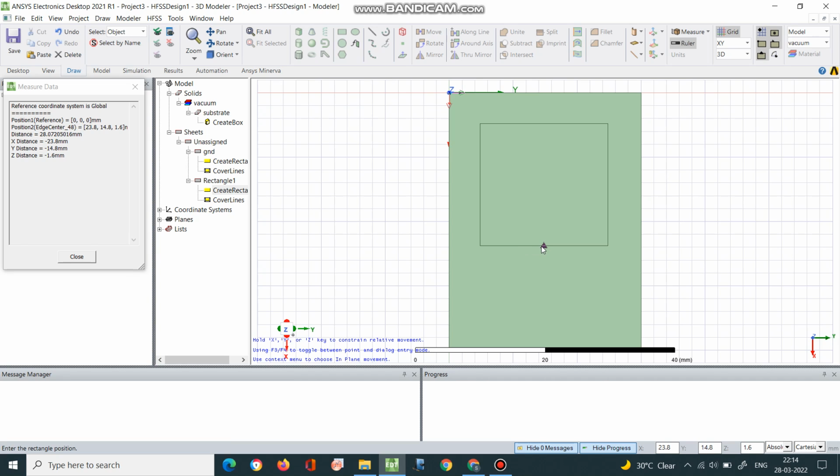For this also I'll be taking the same rectangle. Now when I am changing the position, the shape of the cursor is changing. Here it is like a rhombus, and in the center it is like a triangle. Just for my observation, that is to draw it easily, I'll be starting from the center because at the center I have to feed, but I'll maintain some thickness, right? So let us take the width of the line as 3 mm. But now I have started from center, so later I'll be giving the adjustment as 1.5 mm to the left.